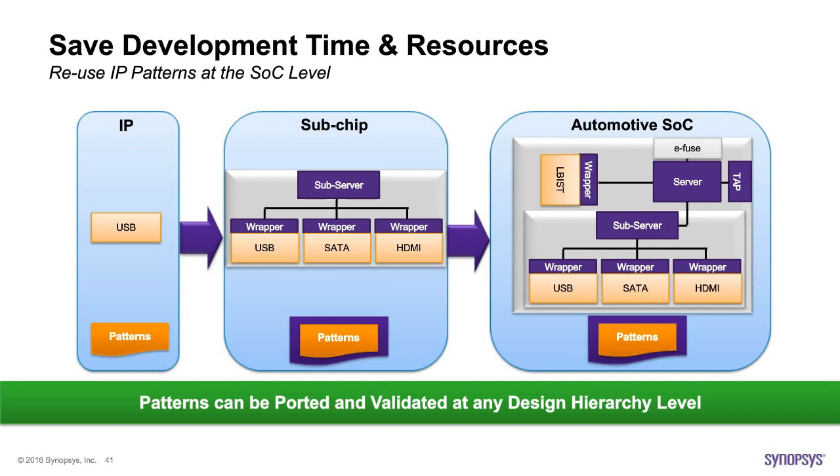Same thing can happen if I go right, to the next one, which is an automotive SoC that has multiple blocks like this. And again, the subserver, which was controlling the subchip, now would be connected to the server that is controlling the entire SoC from a test, repair and safety infrastructure. And it will allow us to take those signals from the IP level, bring them to the subchip level, to the chip level, and report up as necessary.